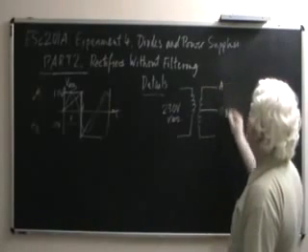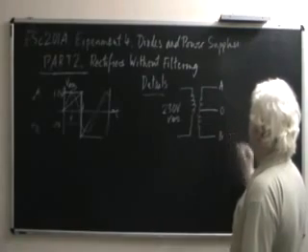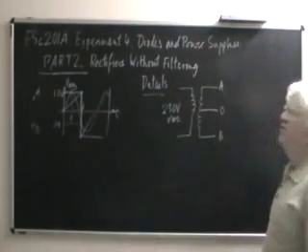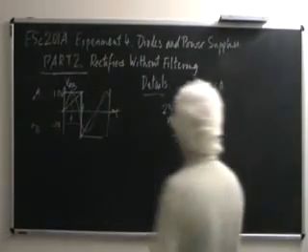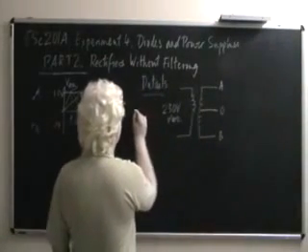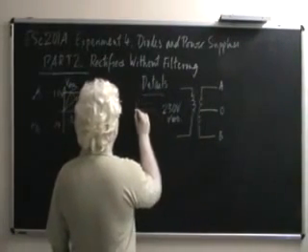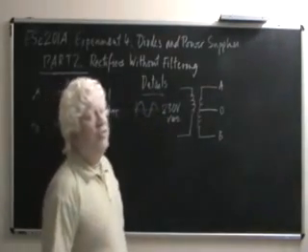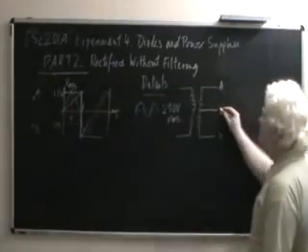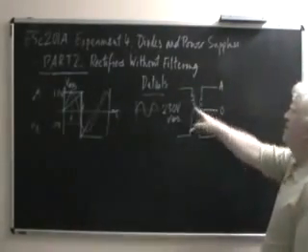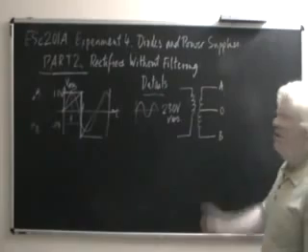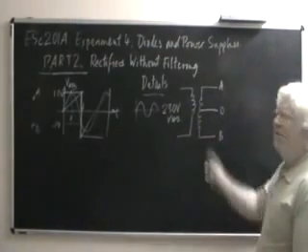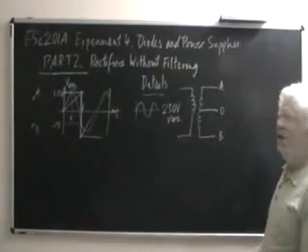This is called terminal A and this is called terminal B. Let us understand what's happening on the secondary side. On the primary side, you have an alternating voltage, a sinusoid, let's say this. This side is electrically isolated from the other side. There is only magnetic coupling between the two sides of this transformer.